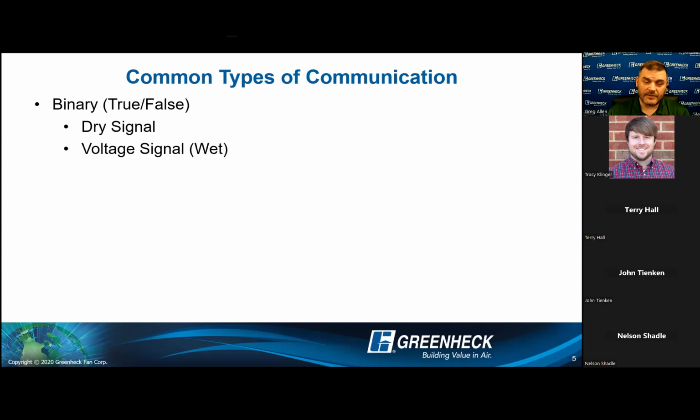There are other devices on that voltage side where they typically aren't using the power at all for anything. They don't power themselves with it. It's powered by something else. It's just recognizing there is or isn't power. And typically that's a 2-wire system where one wire, your common, is 0, and your second wire is carrying a voltage. And it's just saying, hey, they're either both 0, which is stop, or one's 24, 12, 115. It's different than the common. So that's a non-power robbing type system.